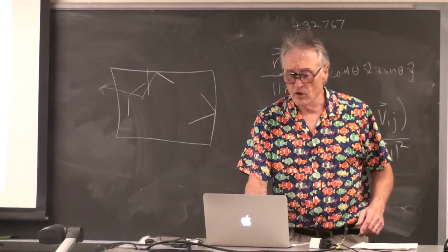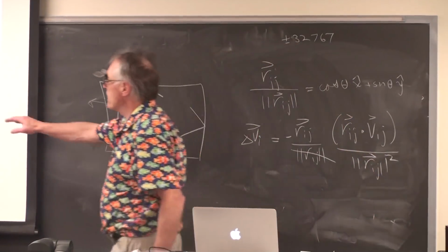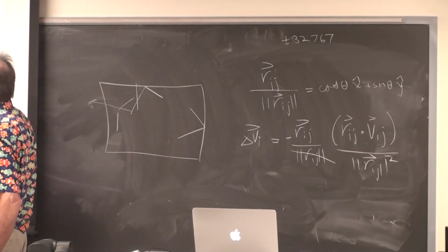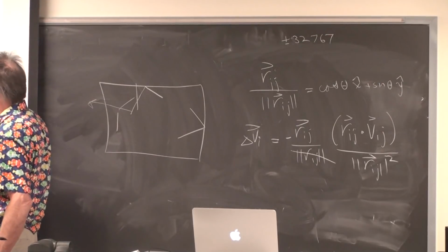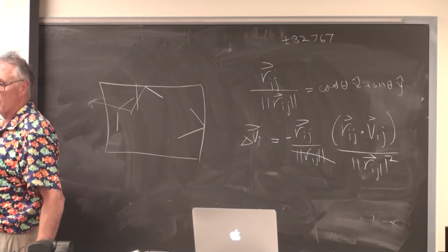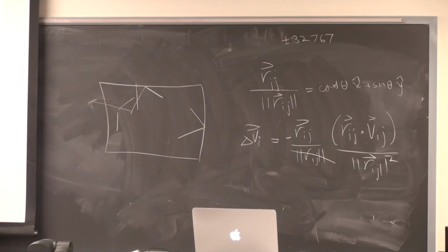So that's the pseudocode from before copied back in. And then inject any new balls into the playing field, if any. Check for user interaction by reading the ADC and buttons, if any. And then do a yield time of 67 minus PT get time minus the begin time. In other words, you're only going to wait for a time which is the leftover of 67 milliseconds after you've done all of the calculation.